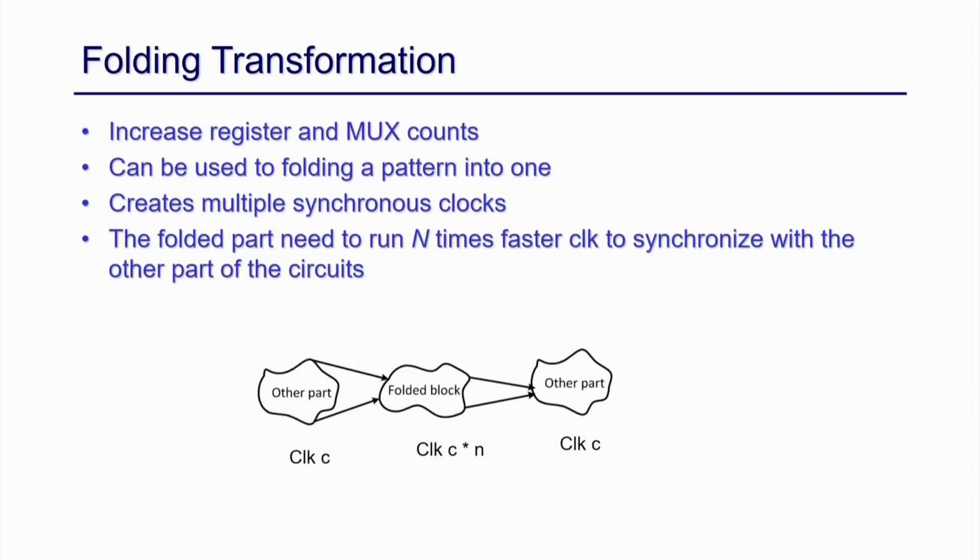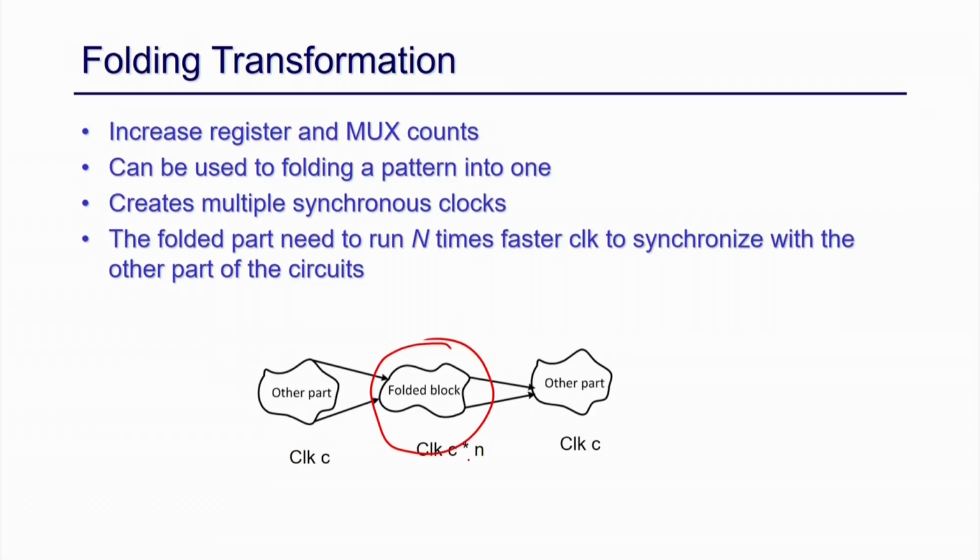The important factor is that, suppose this is your folded structure, but this is not the only component of your design. This is just a part of your design, which is synchronized with the other parts of the design. Earlier, since everything was running in parallel or in series, there was no delay; in one clock you would get the results, right. Now, since this takes multiple clocks, whatever the input coming here, you have to wait for say 3 or 4 cycles to get the output, right.